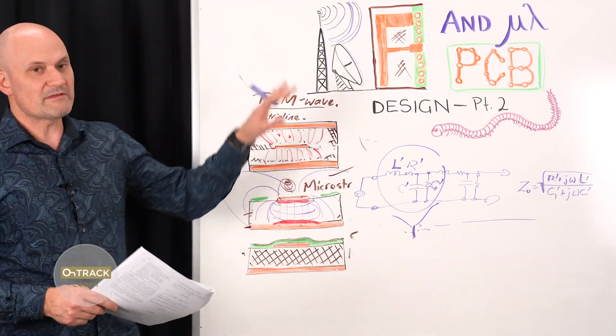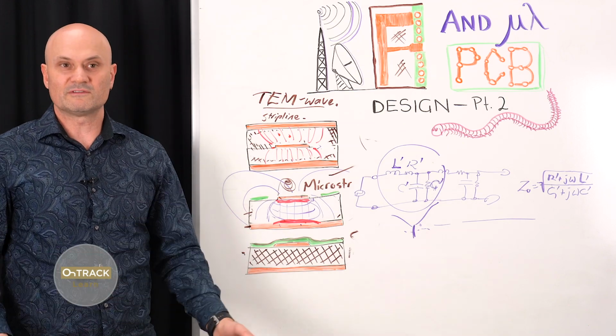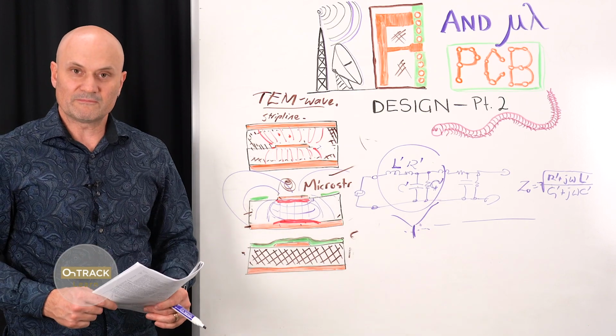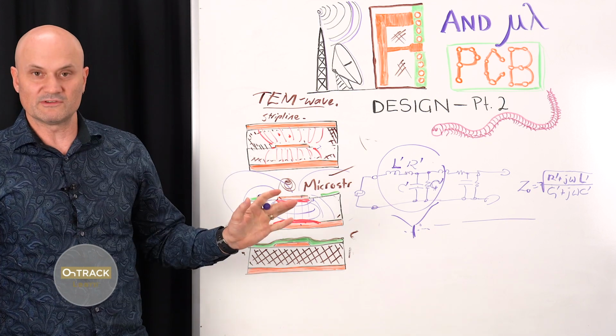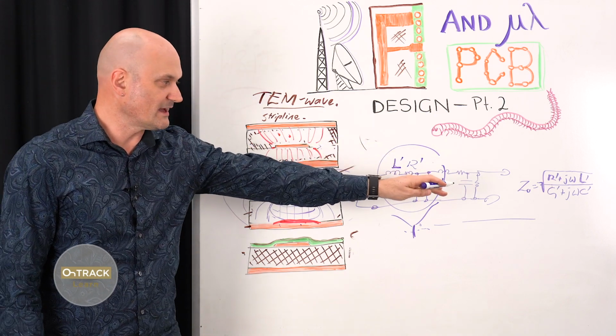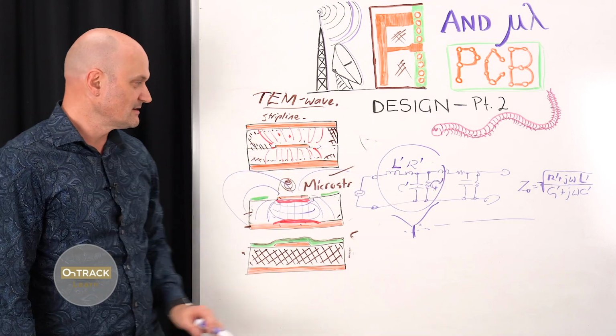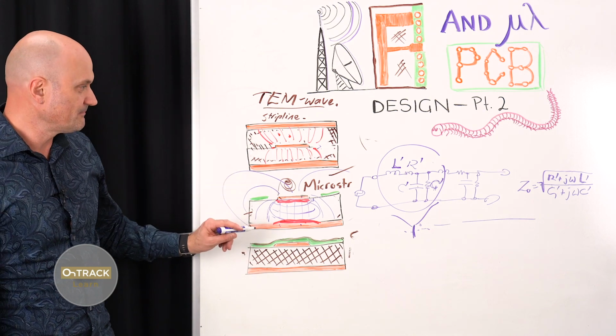And so rather than fill the board full of tons of mathematical equations, I would say check your CAD tool. The PCB layer stack manager in Altium Designer, for example, has an extremely accurate solver for calculating the unit length impedance for any structures and materials you add in.